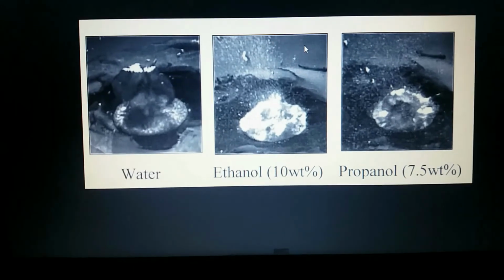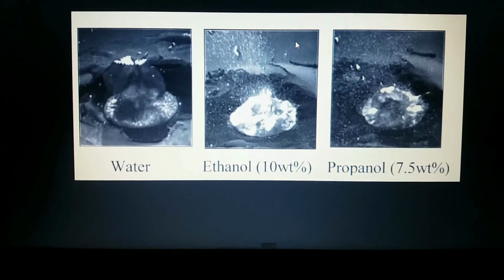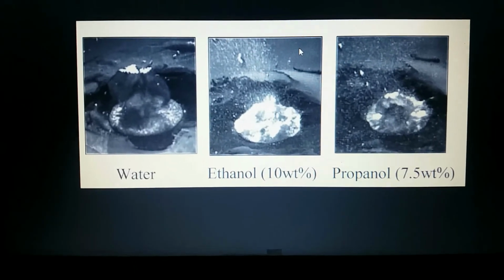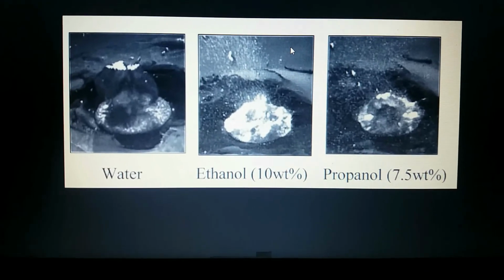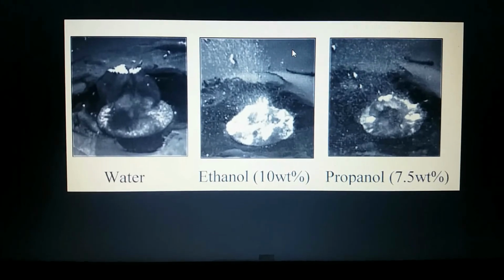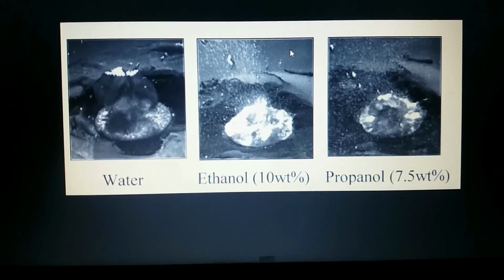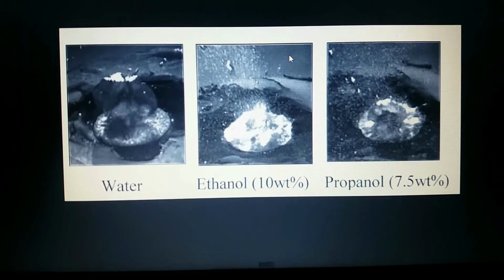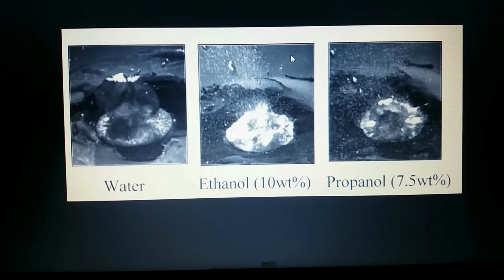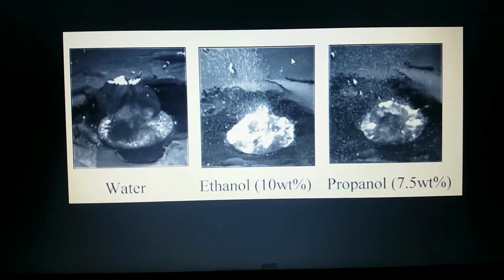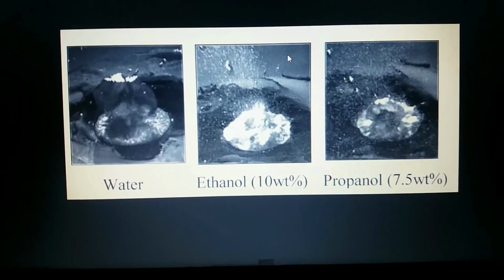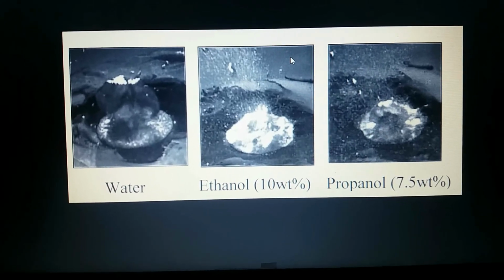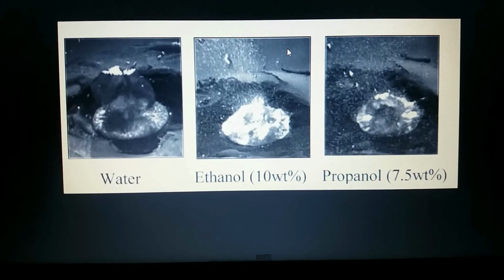Large coalescing bubbles form on the heating surface at CHF and collapse to many fine bubbles at the beginning of transition boiling. The liquid is supplied to the heating surface as the bubbles collapse. The supplied liquid then evaporates and boiling bubbles again expand to large coalescing bubbles at CHF. The process is repeated rapidly and the heat flux exceeds the critical heat flux.